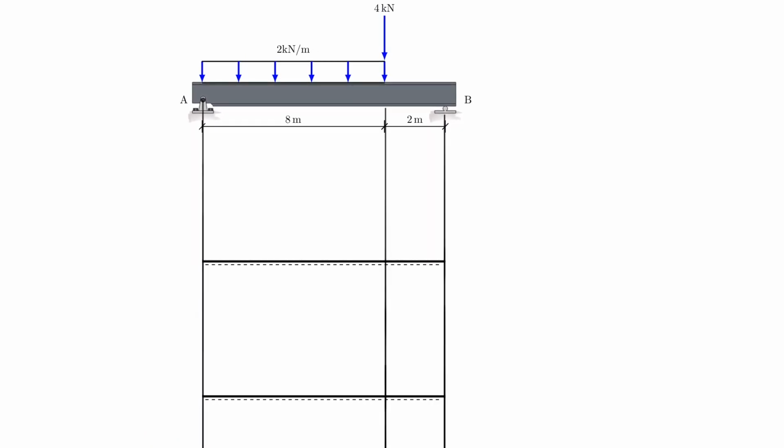Let's start with the shear force diagram here on the top. This is the shear force in kilonewtons. I remember that on the left side, I had a value of plus 10.4. You can plug in values now if you want to, but remember that we went through 0 at 5.4 meters, I believe, if memory serves correct.